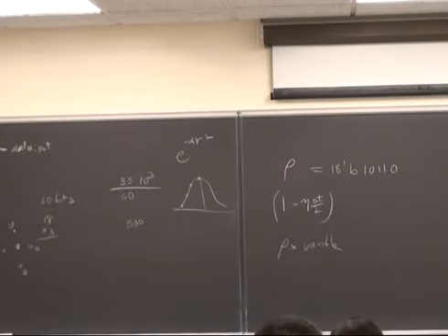This does bring up an interesting point, though, and that is you press a button, and that means that, in principle, once you press the button, you may need to load a separate value in each of 100 nodes. And so you need a mechanism to do that. If you have separate state machines for each node, well, then it's like pressing reset on the state machine. It's going to load up the registers in the state machine with some value.